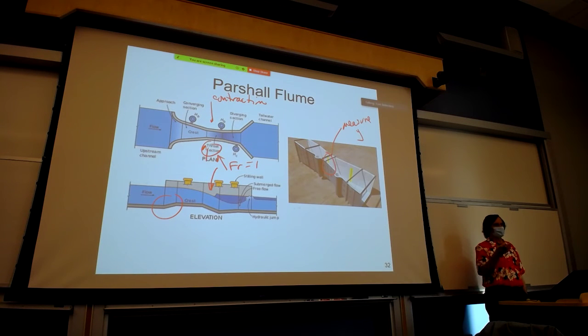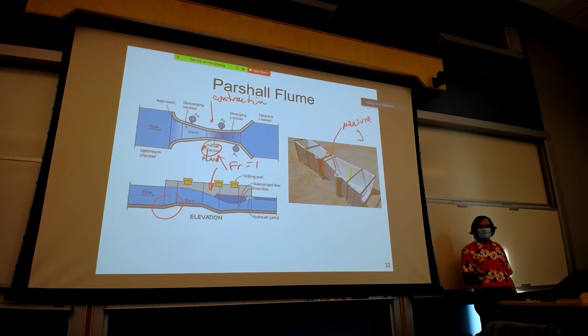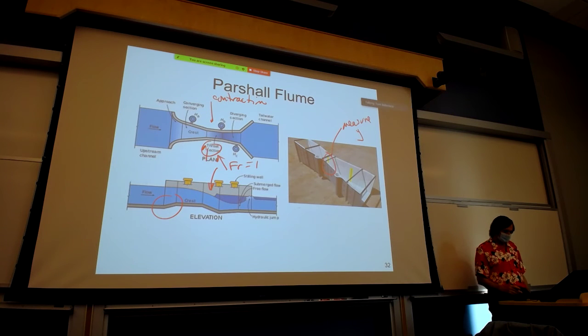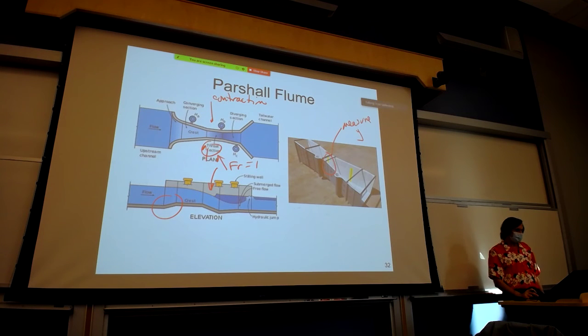And so very often in open channels, we actually may be stream gauging, just like Professor Kinnan had you do in ENE 400. You would go out and measure the velocity across different locations across the stream, multiply that by the cell width times the cell depth, the water depth in each cell, times the velocity, and you calculated the discharge across the stream. It's a lot easier with the flume.